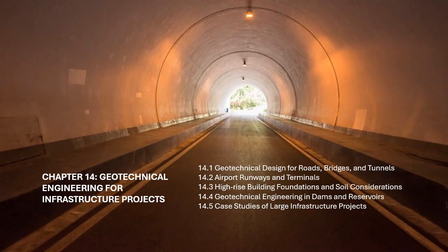The foundation for the new locks was designed using gravel-filled embankments and reinforced concrete structures to provide stability in the highly variable and seismic-prone soil conditions. Geotechnical innovations. One of the key innovations was the use of deep soil mixing techniques to improve the strength and stability of the soil at the base of the locks. This process involved mixing cement and other stabilizing agents into the soil to create a stronger, more durable foundation for the locks.